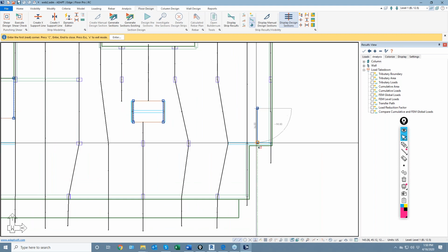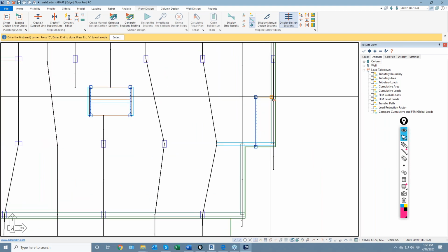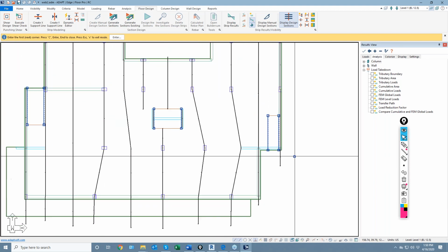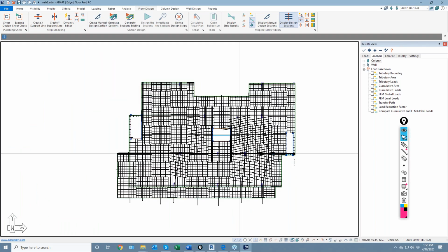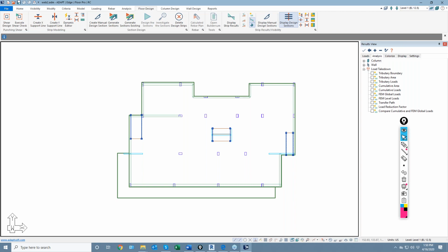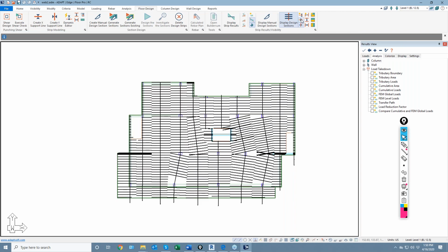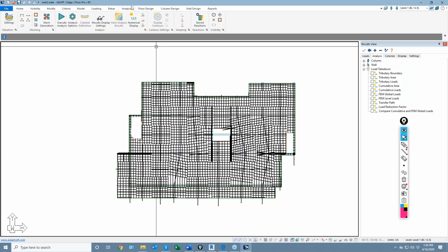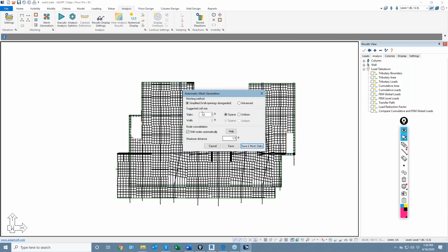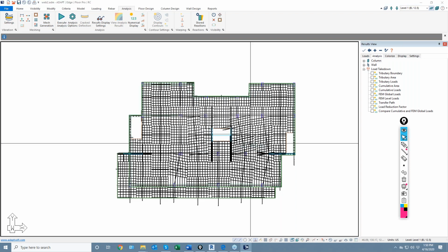And so we'll place the splitters in the same direction mainly as the support lines themselves. And now I'll generate the cuts, and let me turn the splitters off. We're left with our Y cuts now and our X cuts. Okay, those are the design cuts. We're now going to come back and mesh this. I'm running low on time, unfortunately, so today we're just going to mesh this as is. We'll just use the default settings here. I'll mesh the slab,